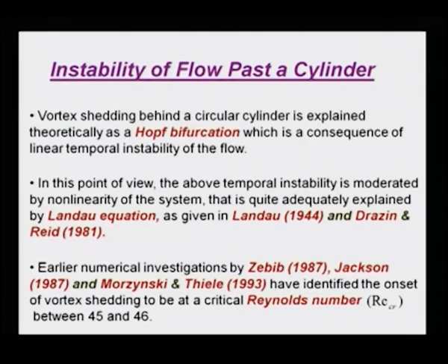People have called it a Hopf bifurcation as a consequence of linear temporal instability. The above temporal instability is moderated by nonlinearity, which can be explained by the Landau equation. You can read it in Landau's original work or in Drazin and Reid's monograph. Some numerical investigations have been done in the mid-80s.